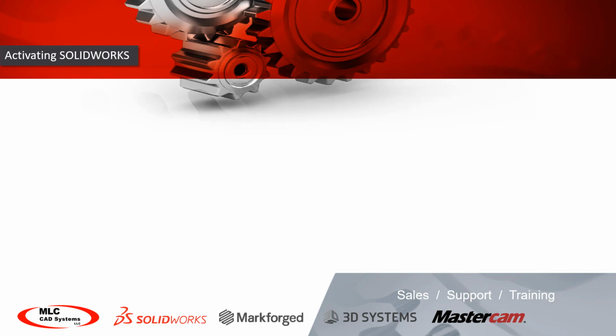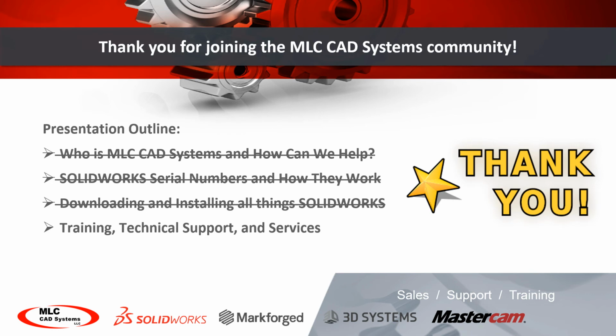Of course, once you've got it installed, it's time to activate SolidWorks. So just launch it for the very first time. The activation wizard will come up, enter your email address, and hit next on the prompts, and you'll be activated and ready to go. Remember, if you ever need to move SolidWorks to a different machine, you don't have to uninstall it. Simply hit help and deactivate, and your second machine will be ready.